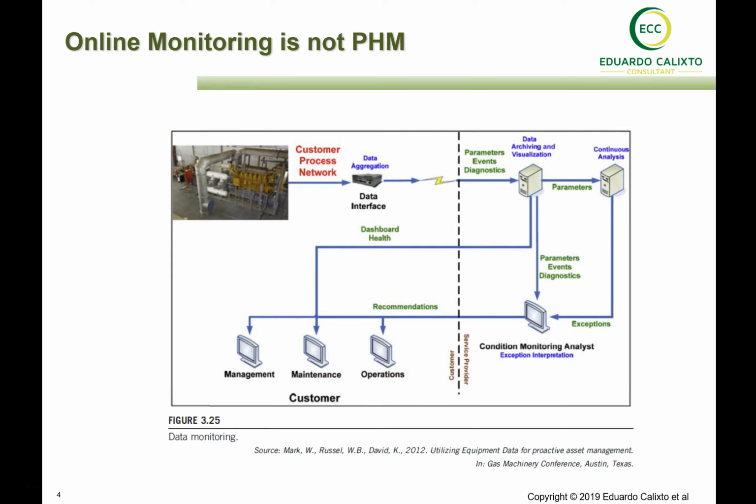Basically, vibration is one of the physical parameters that impact different components and can trigger failure. So what's going to happen is that such a sensor will be associated with a data interface system that will go to a server, and then this server will present the information in graphs about the level of vibration the compressor is facing during operation. Whenever it reaches an upper level, the maintenance and operations team need to take some actions.